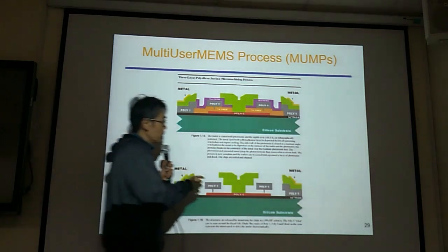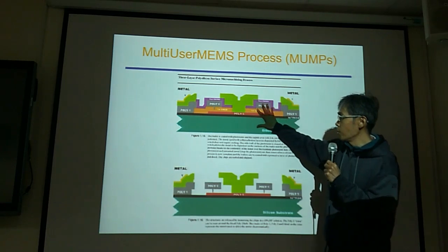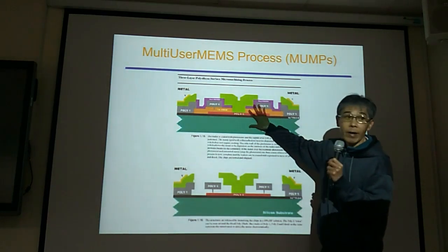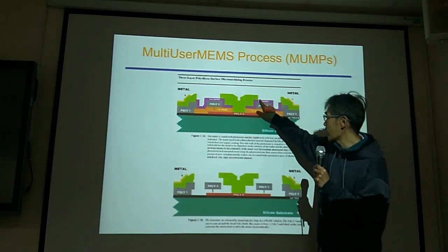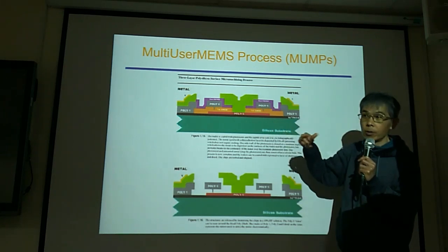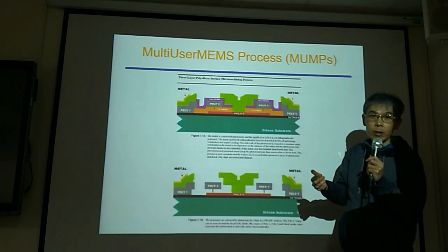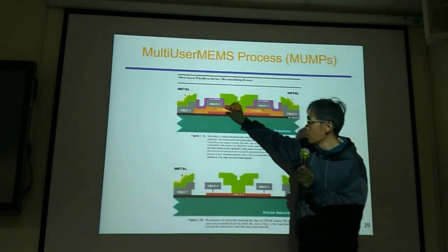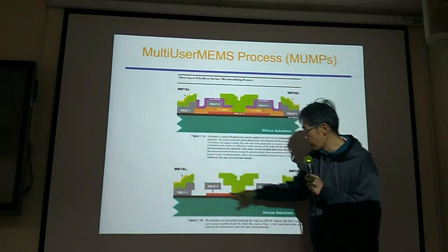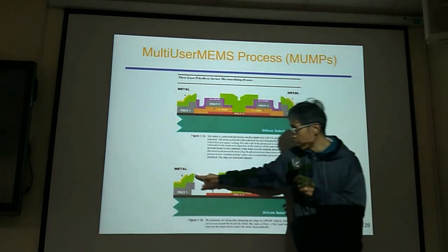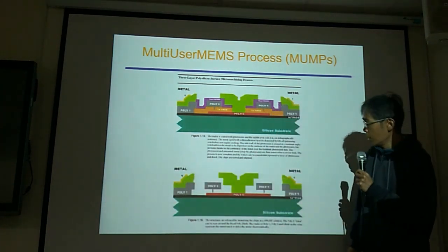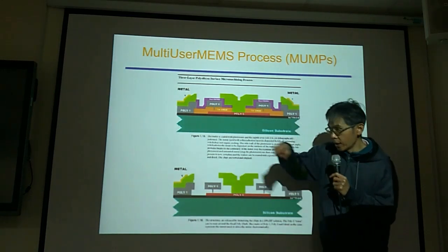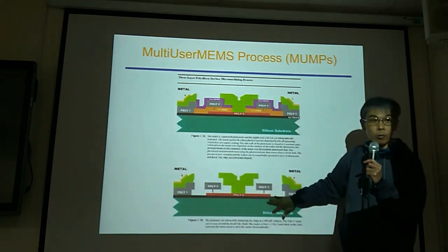See, this is what I mentioned. This is the rotor device. After the micromachining process, in the end, we got a device like this. Then we have oxide, and we remove the oxide. We can use HF etching, oxide etching with HF, to remove the oxide. If we remove the oxide here and here, we are left with the polysilicon structure. Polysilicon, and this is metal, tungsten or aluminum. This is the cross-sectional view. This one is the rotor. This is the center, and this rotor can rotate. This is a micromotor. Can you imagine this?